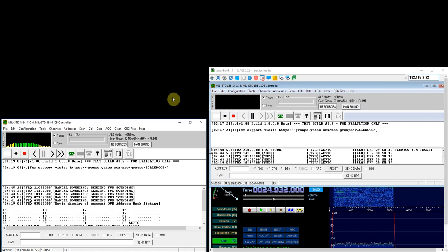But the scenario I'm talking about involves portable antennas, portable stations, and perhaps you're not well equipped for these rapid and automatic band changes. In that case, this is one way that you can first of all test the conditions on each of the bands, and then make a choice based on the soundings for each of those bands, and then somebody who's got the role of net control would send out a message to all the other stations announcing the desired band. And I'll go ahead and once again illustrate how to send that kind of message.